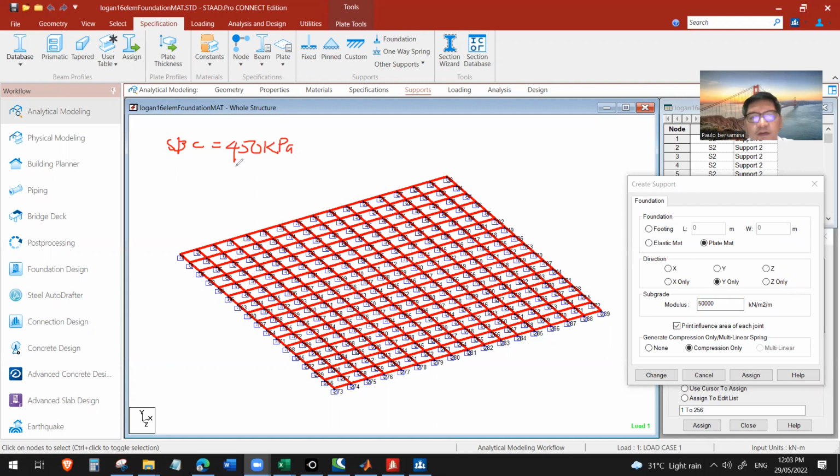No? 450 kPa. So kasi when I was a geotech, let's say we come up with an SBC of 100 kPa. Yun yung mga typical, no? Pag mga residential or 90 kPa. May ano kagad dyan. Automatic, ang allowable settlement niyan is around 25 mm. So, ganun kagad, no?